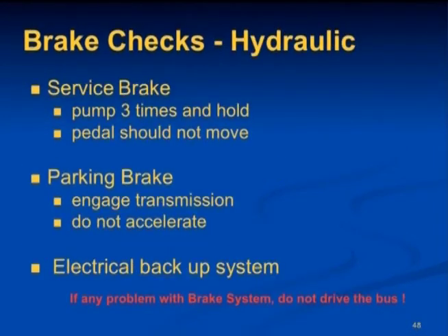Okay, let's take a look at what you would check if you had hydraulic brakes. If equipped, check the anti-lock braking system indicator lights. Again, those lights should come on and then turn off. Pump the brake pedal 3 times, then apply firm pressure to the pedal and hold it for 5 seconds. The pedal should not move. If it does, there may be a leak or other problem. Get it fixed before driving.